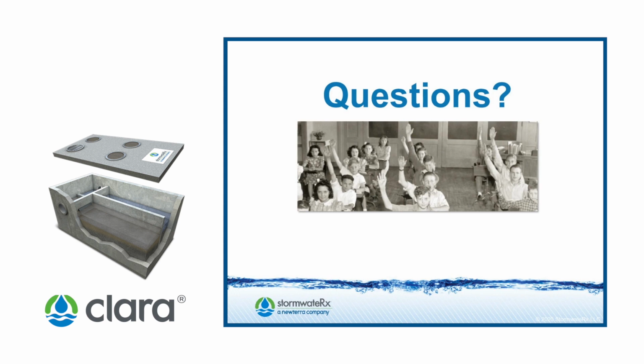There is no loss. We'll get oil removal both from adsorption to the media, as well as it being trapped in the second and third chambers of the filter, just by phase separation, essentially. So the system is not exactly designed for high capacity oil removal, but it will sequester oil within the system. And so the removal is just, during the maintenance procedure, when the water and media are removed, you'll get that trapped oil out as well.